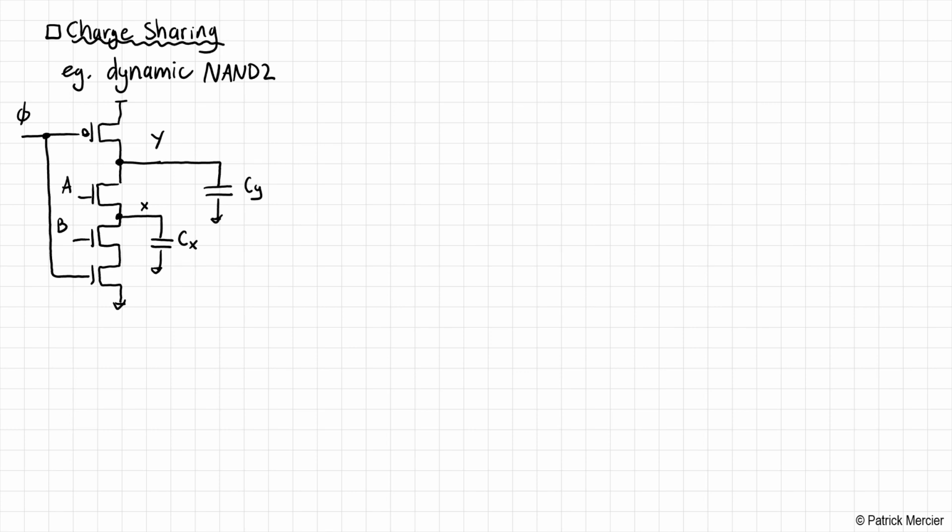Okay, now let's imagine that during this example, input B is equal to 0. All right, and let's say that Vx was equal to 0 initially. So perhaps in the prior phase of the clock, the pull down network had pulled everything down, and Vx was equal to 0 in this example. Then we say A goes from 0 to 1. All right, so what happens? Let's take a look at our timing diagram.